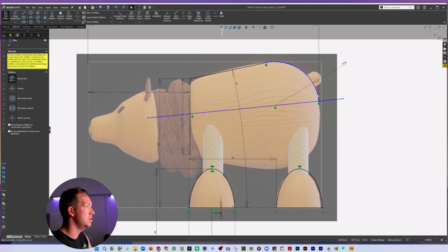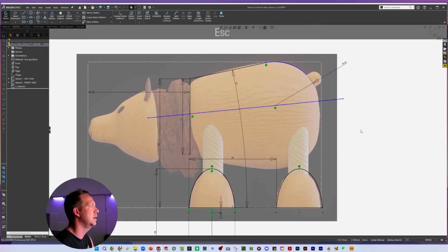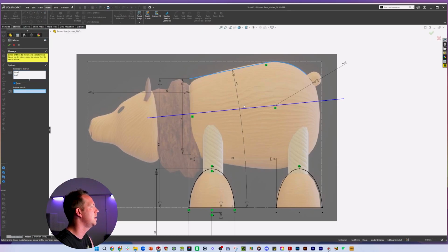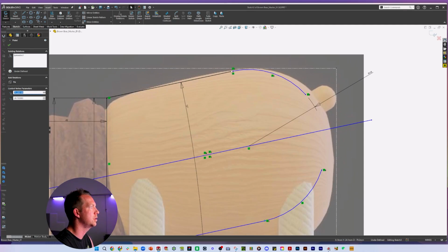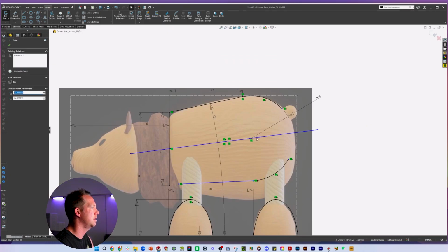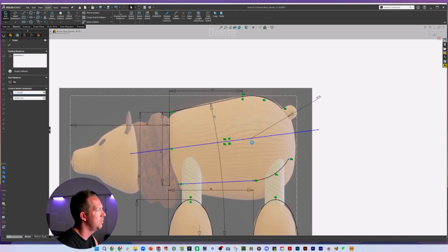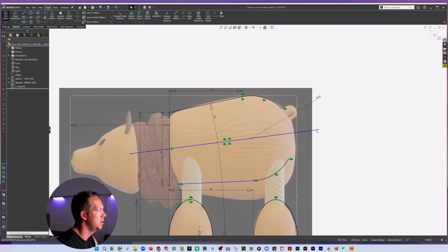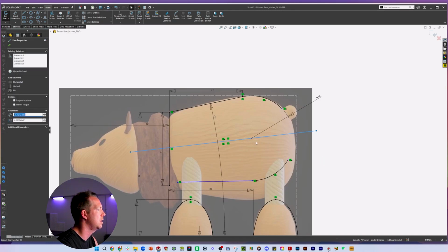If this one here is not a true single radius, there's actually one in the middle. What I'm going to do is try again. I'm going to bring this one down. Actually, what I'm going to do is fix that one in that point by giving it a dimension. So what that lets me do now, I'm going to move that, delete that relation and just try and move this mirrored line. I think I am struggling to do that.